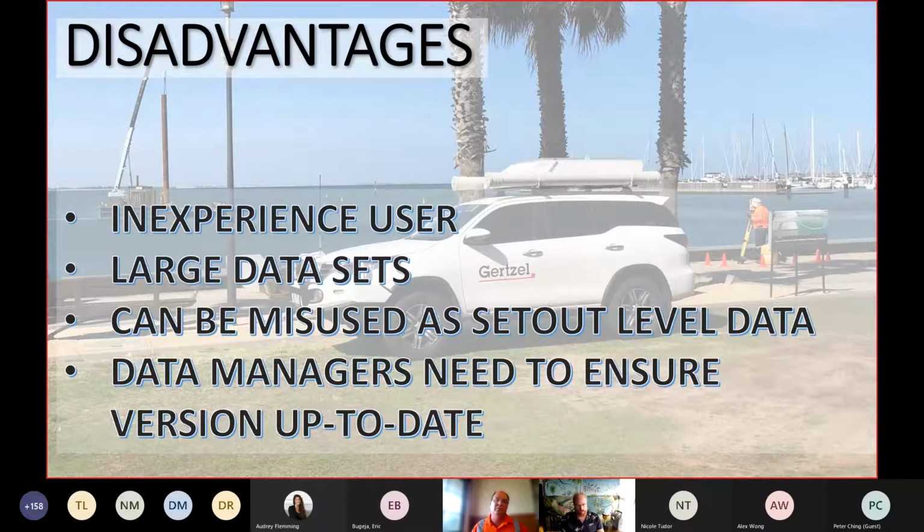And with the IFC file, what's been brilliant about that is it comes across the same in all of these formats. So if I'm using MicroStation, or 12D, or Trimble Business Center, spatially and aesthetically, it comes across looking very similar, which is really important for us in the way in which we handle the data. The other part that I haven't probably addressed here is also the attribution of the data. So we're actually at the moment going out and recording services with attributions to allow the designers to create themselves a really nice IFC BIM file for services. And we're managing that both in 12D and Trimble Business Center and MicroStation, and because it's an interchange format, it's been really easy to switch between all those platforms.